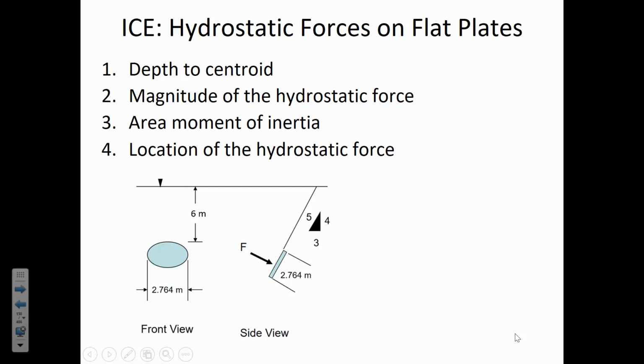All right. So what's the difference between Y bar and delta H? Well, delta H is a vertical measurement from the centroid straight up to the water surface, and Y bar is starting at the same place at the centroid, but it's going along the inclined path to the surface rather than straight vertically up. So you'll have to differentiate between the Y bar and the delta H in this problem. All right, so let me hand out the paper for this one.